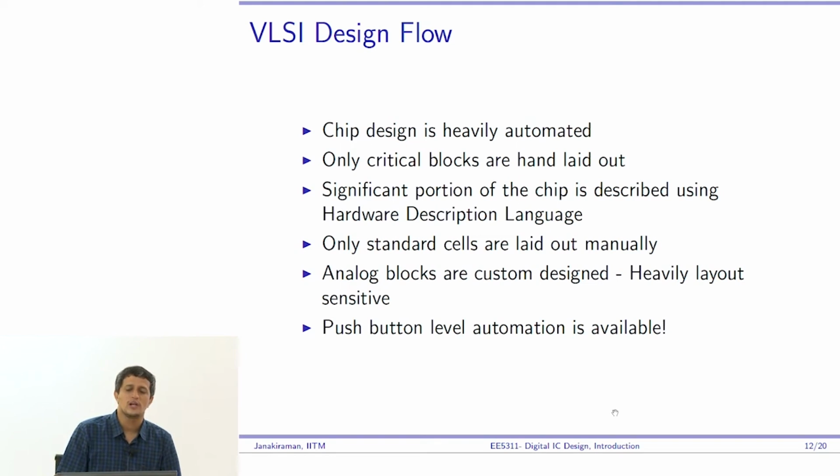Only the critical blocks are hand laid out, which in this course you will do only hand layout, you will not do synthesis. A significant portion of the chip is described using hardware description languages like Verilog and so on. Only some select things called standard cells, I'll tell you what they are, are laid out manually. Analog blocks are usually custom designed. So it's like a push button now.